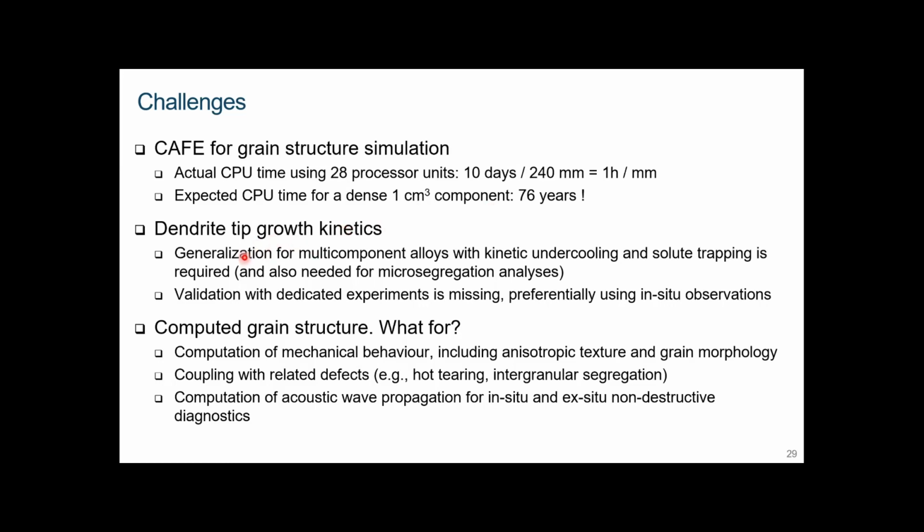For the dendrite tip, we need to generalize for multi-component alloys the kinetic undercooling due to solute trapping, and we need more validation with dedicated experiments. I think these new in situ observations are something really unique for that. I hope we will have more.